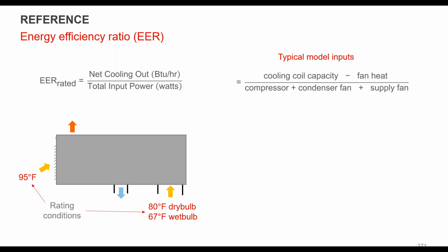And if you're going to submit a LEED model or a compliance model, you certainly will get a comment on this from the reviewer. But the EER is a rated tested condition at 95 degrees with 80-degree dry bulb return and 76 wet bulb return, right? So it is a fixed tested condition.